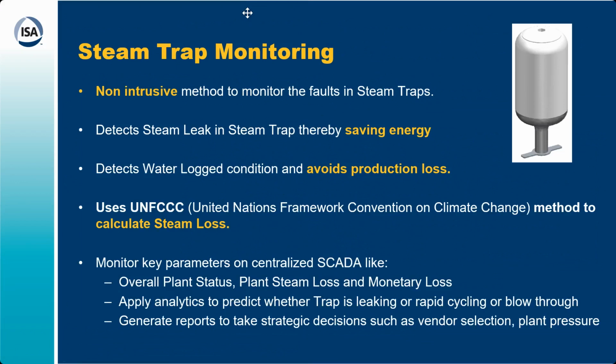The HART communication standard has evolved in such a way that it becomes backward compatible with all the instruments, because most of these gateways also work with instruments installed in the 90s, and you can get the data of HART version 5. The only thing is that they might not have the best kind of analytics available in their HART communication platform.